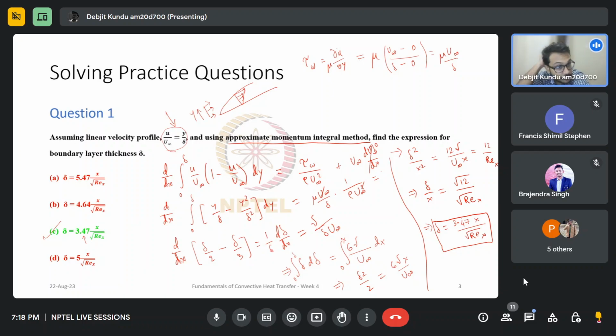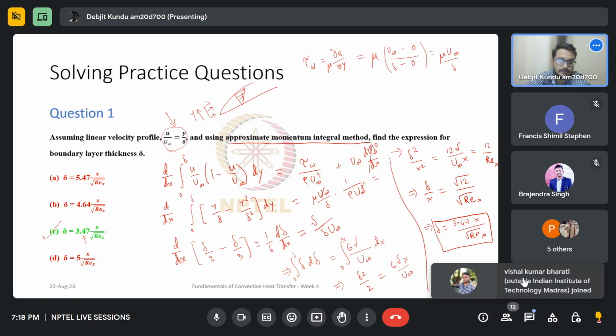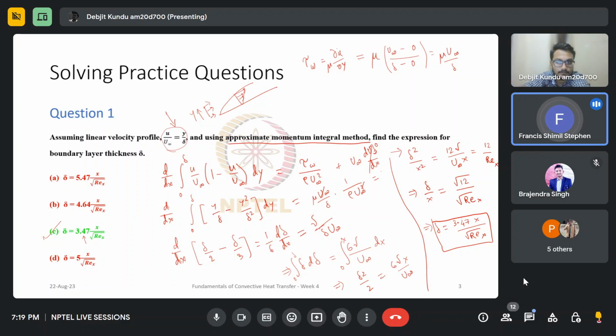Wherever you saw that the von Karman integral method has that solution, try to check which velocity profile they are assuming. That would be the important determinant over here. In my note, actually, u by u infinity is taken as 3 by 2 y by delta minus 1 by 2 (y by delta) cubed. So there a cubic profile is assumed.